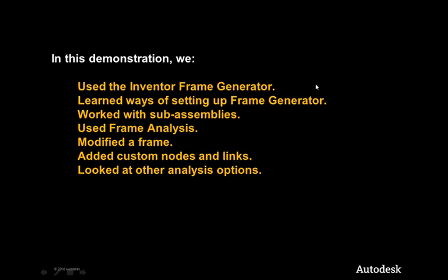What I've shown you is a very simple use of the frame generator with a few tips and tricks, I hope. We've learned ways of setting up the frame generator. We've worked with sub-assemblies. We've used the frame analysis software. We've modified the frame. We've added custom nodes and links. And we've looked at other analysis options that we have available to us if we don't have Inventor Professional.